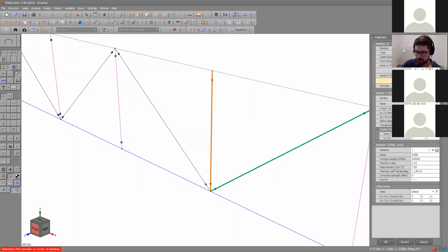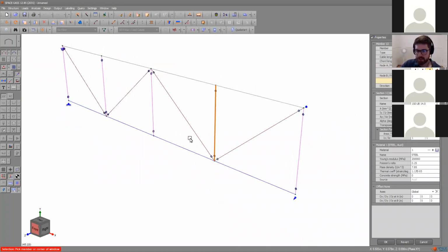But as you're learning to use it, the reason I pointed this out is the two most common errors you're going to get if your models don't run. You'll get an instability error here because you've released torsion, and that means some element is free to rotate without load. So I would rarely release torsion, which is this last item here. Simply release rotation about the z-axis if you need a truss element.